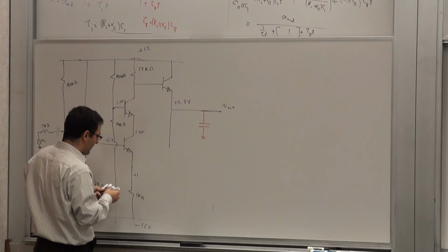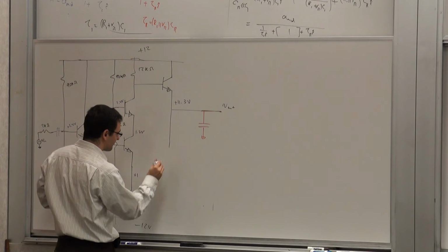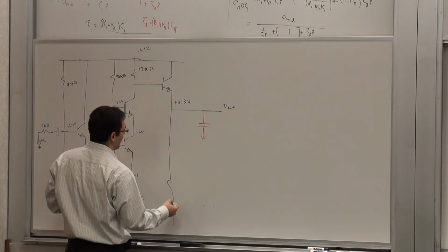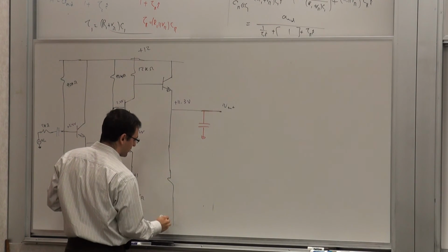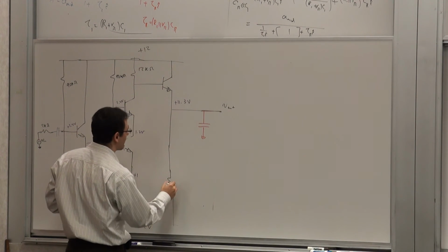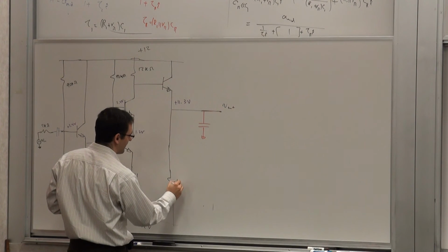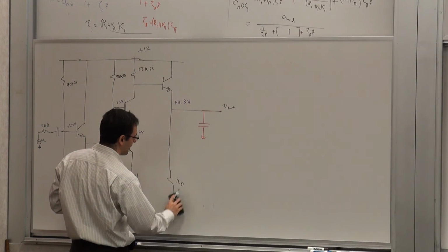And if I want to bias it at 1 milliamp or something, then I can do it. Typically I would probably bias it higher than that 1 milliamp because this is driving the output, but it doesn't matter. Just for now, we can make this 11.3 kilo ohms.